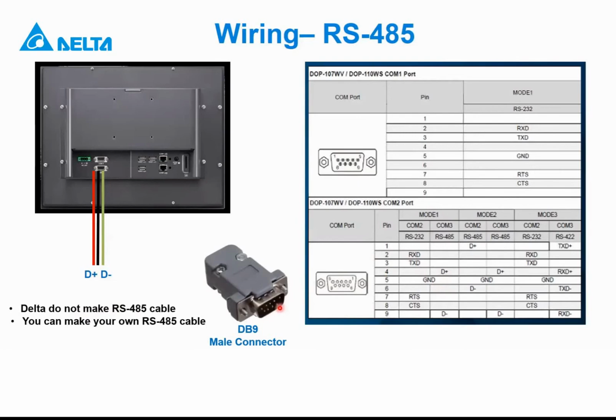Depending on the connection you want to make, it's quite flexible. You can use this guide to choose your connections. You can use mode 1 communication, mode 2, mode 3. Each mode is defined by the type of pin you use. When you connect the correct pins in each of the modes, like RS-485, then you can communicate with the controller that you want using the RS-485 communication protocol.